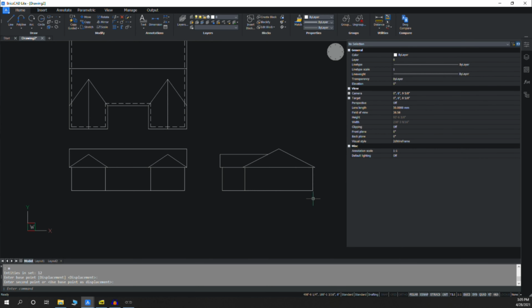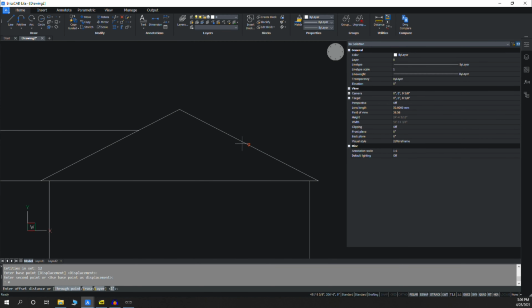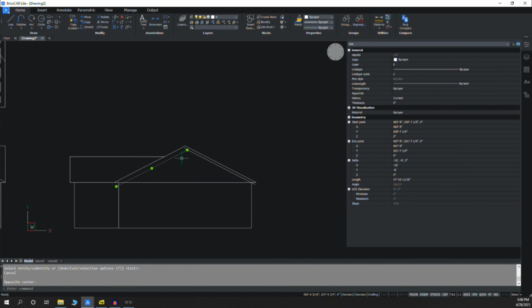I really just wanted to go over the basics of how to get the rough structure down. You can go in later and draw in things like the fascia. So you want like a 6-inch fascia board. And as you start to put these details in, it'll look more and more like a roof. But this is geometrically correct now.